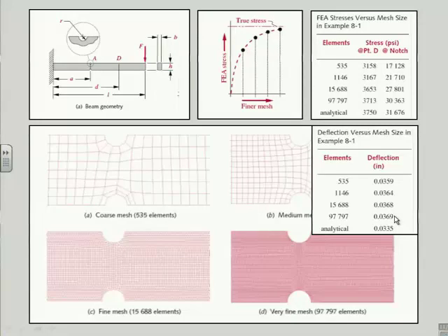I'm sorry? Transverse and lower? Yeah, you've got transverse shear and you've got the bending, right? Well, it turns out that the way the equations are derived for the deflection, it ignores the transverse shear. It just considers the bending. So the contribution to deflection of the transverse shear is missing from the analytical solution. And it's present in the FEA because everything's in there. So in this particular case, it turns out the FEA is a better answer.